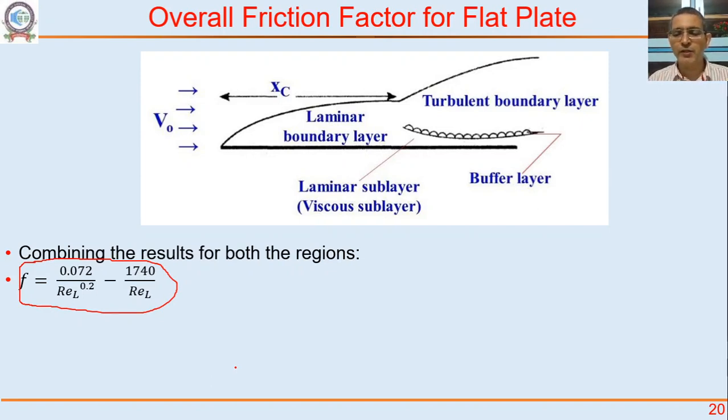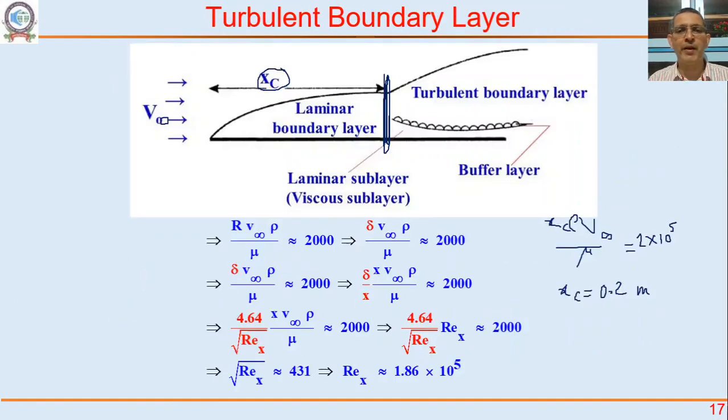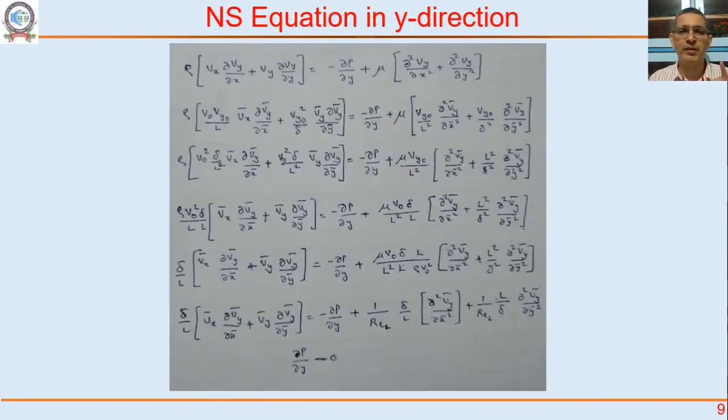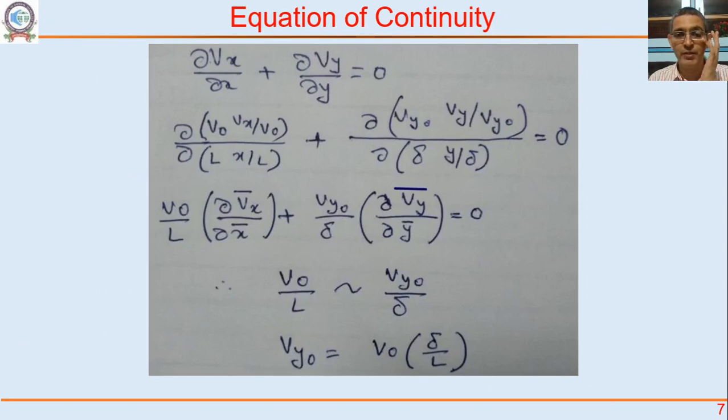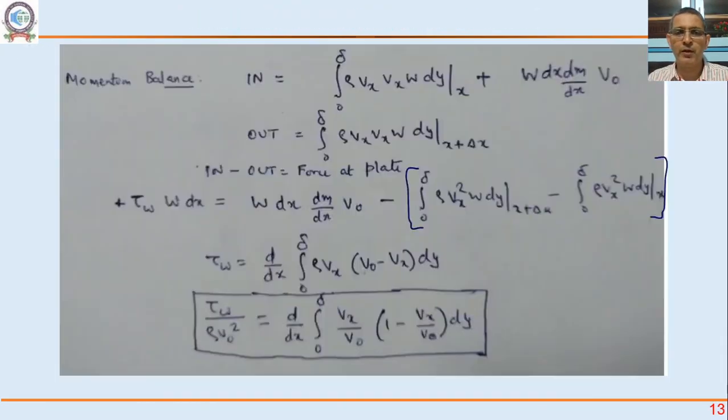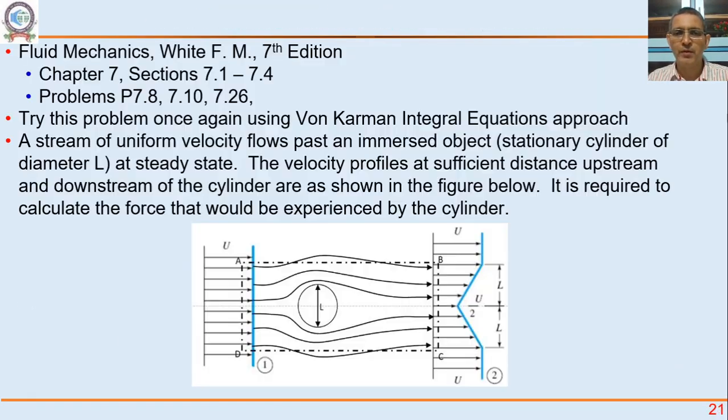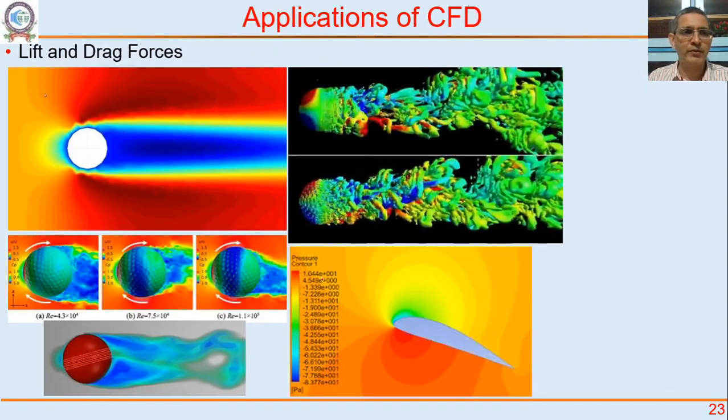Whenever, one word of caution, whenever boundary layer is separating, right, let me put that. You see, delta by L is small. Whenever boundary layer is separating, we call it boundary layer separation. I'll just show you some profile, which we'll talk about later. Suppose boundary layer separation is happening here, right? Now delta by L is not small.